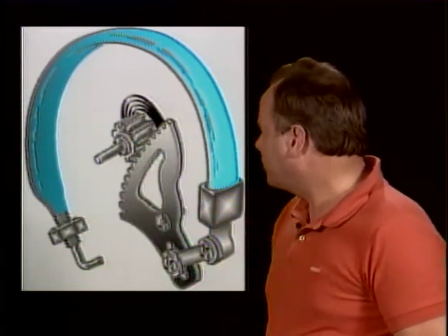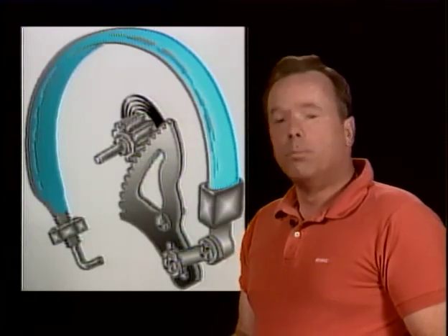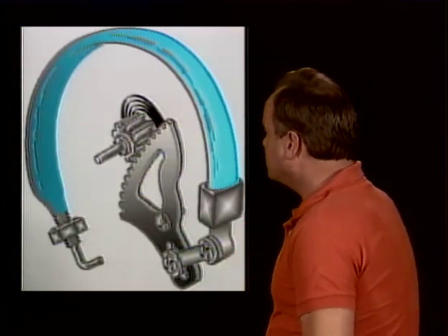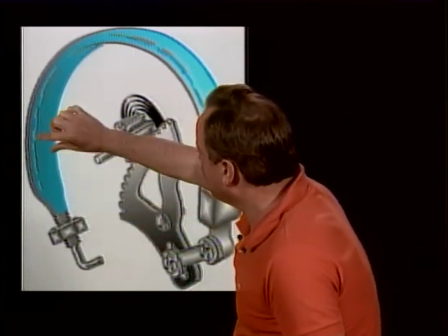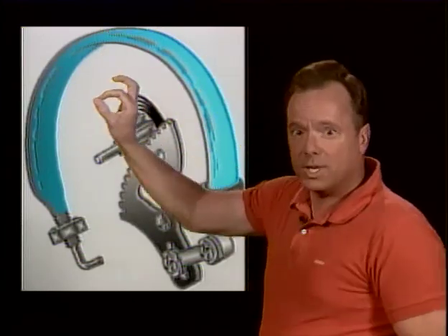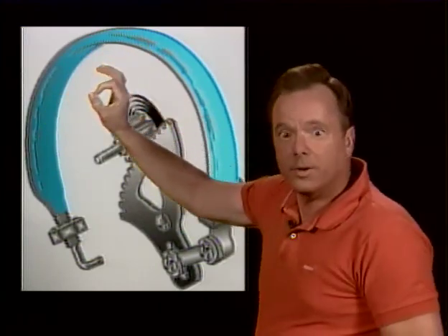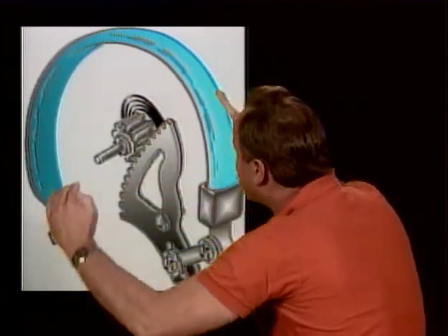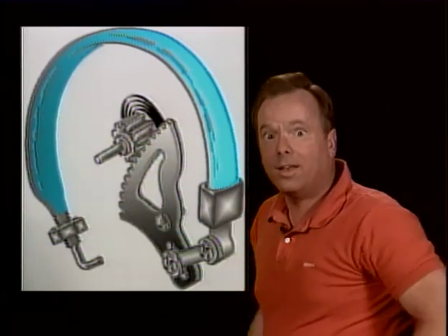All right, now, they're going to ask you about construction and design of various type gauges, and they're going to say instruments that provide readings of pressure of about 10 psi, such as pressure gauges and oil pressure, are usually of the Bourdon type. And here is a Bourdon type gauge. The way a Bourdon type gauge works, by the way, is you have a pressure inside this tube, which has kind of an elliptical shape. When the pressure increases, the elliptical shape of the tube wants to become circular instead of elliptical, and that wants to straighten out the tube, and you measure the rate at which the tube straightens out on a dial, and it tells you the pressure.